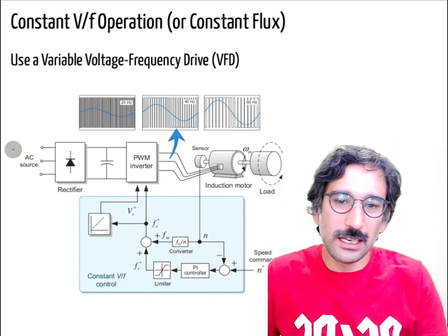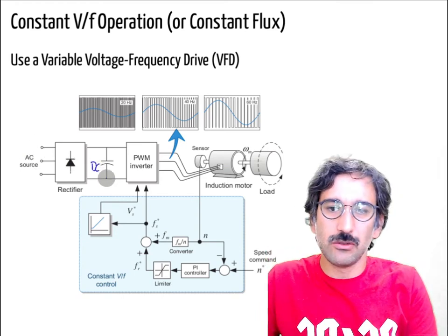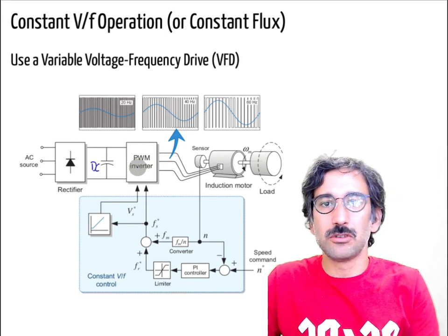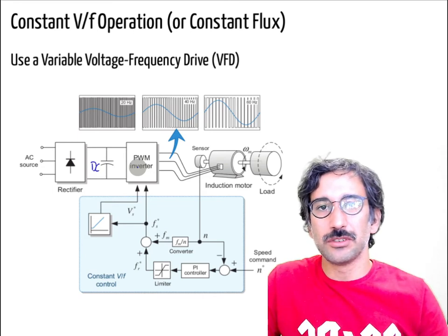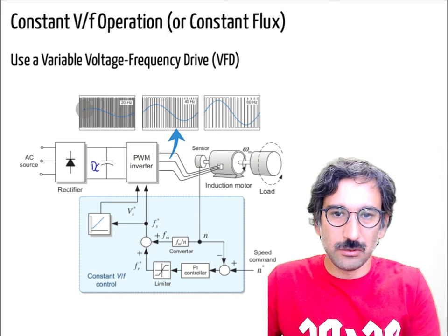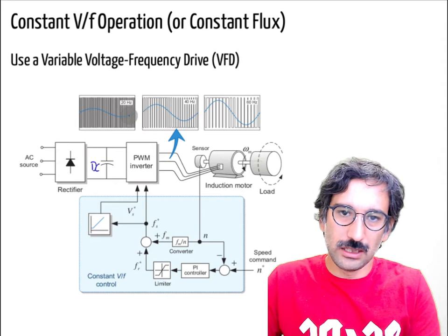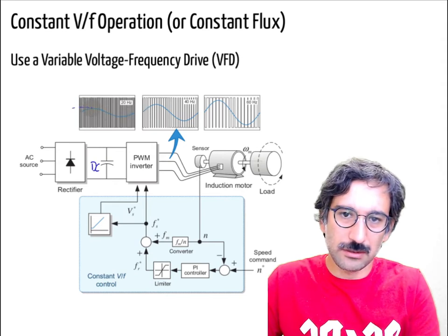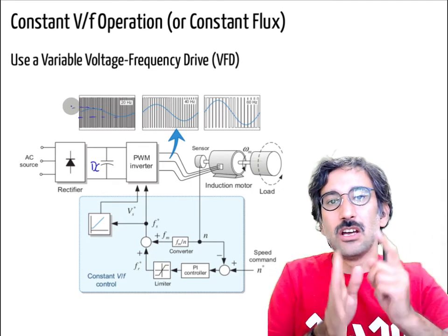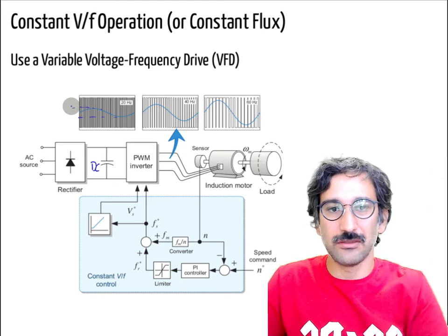So an AC to DC converter here, then you will have a DC voltage there, then a PWM inverter, and that PWM inverter can generate any voltage and frequency. If you look here at 20 Hertz, it generates a small low frequency signal, and its magnitude is lower, but it is generating that voltage with on and off voltage waves, PWM signals at a high frequency.